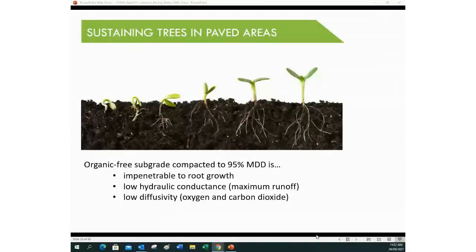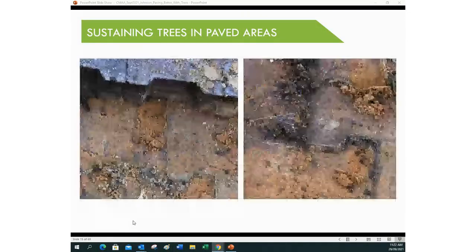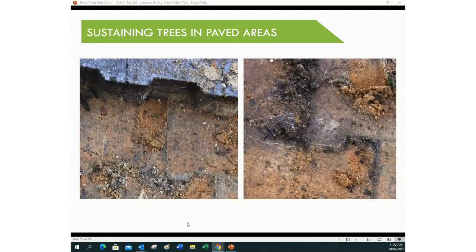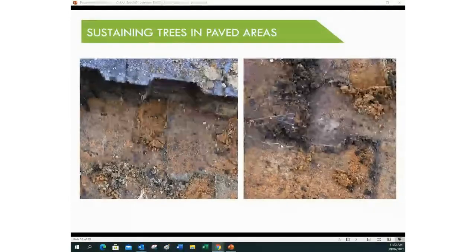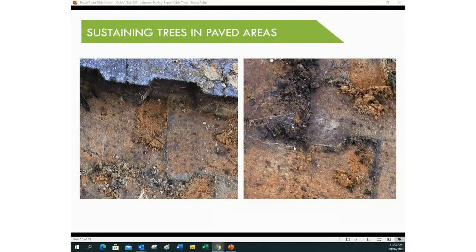So what we need is soil that can support root growth. And there you see some sand under some typical impermeable paving. You can see these white fibres here. That is the propagating root. The extending root is at the tip of those. Sand is very granular, high pore spaces. Roots can easily divide in sand, even if it's compacted under paving.